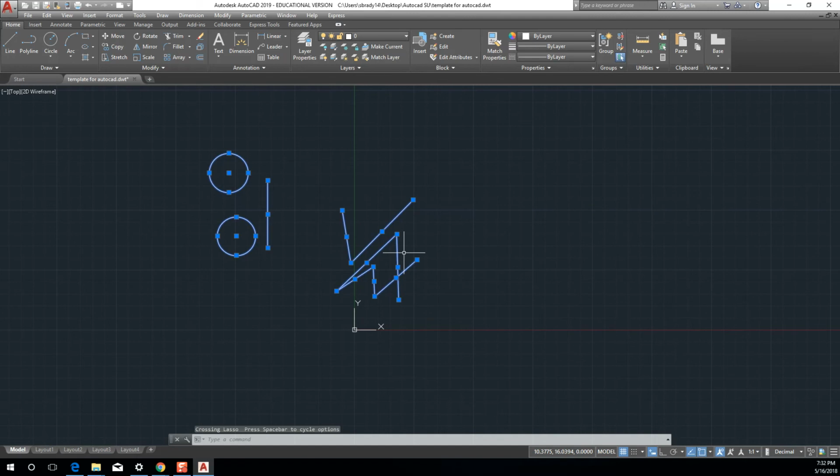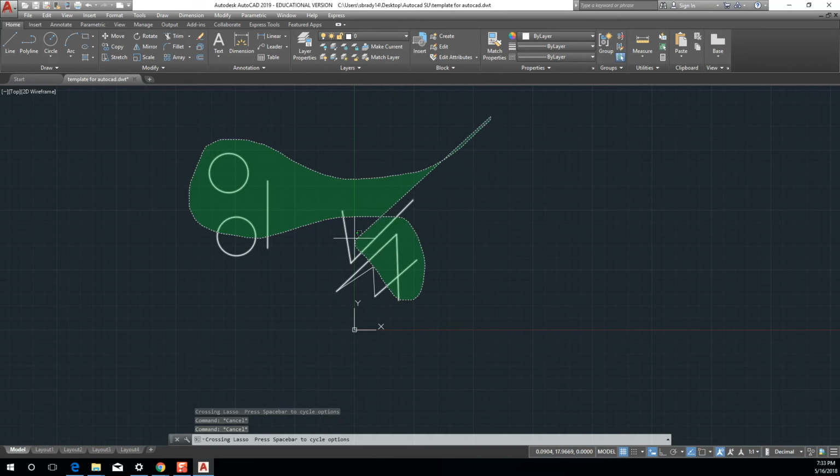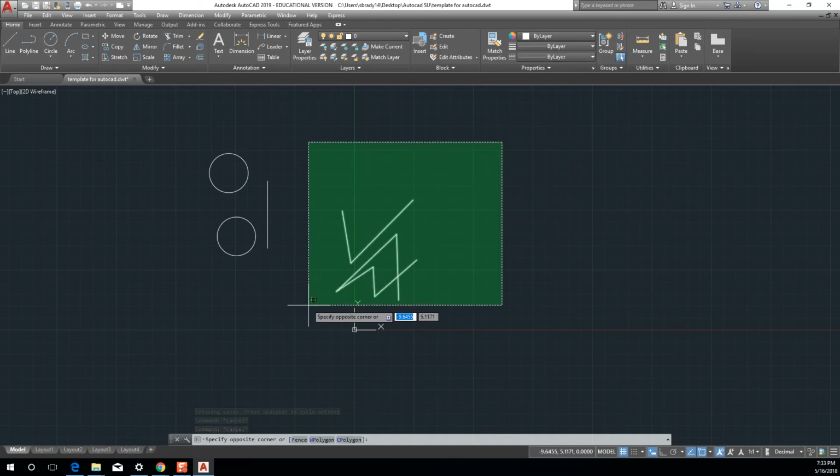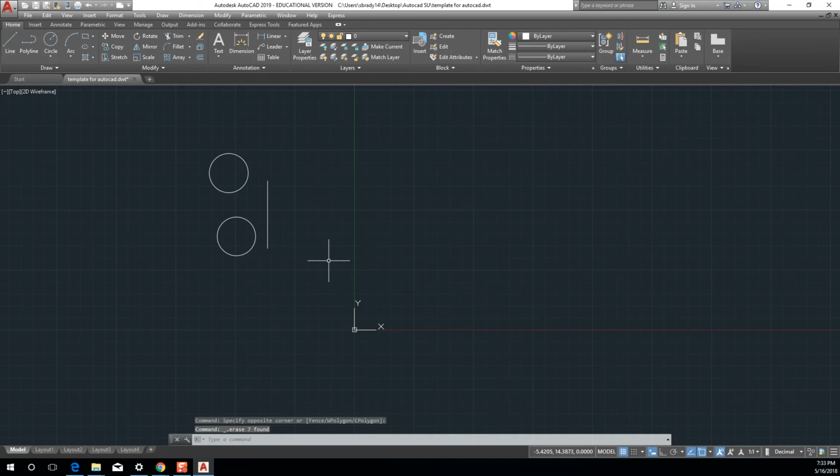It's the lasso, right? So you can select things with it, but I just don't prefer it. We'll say that. You get quite particular in what commands you like in AutoCAD, right? So not my favorite, but if you click and you hold and you drag around, you could do that. Escape, escape. But again, I kind of like the selection window where I click, I move over objects, I click again, and then I hit delete, right?